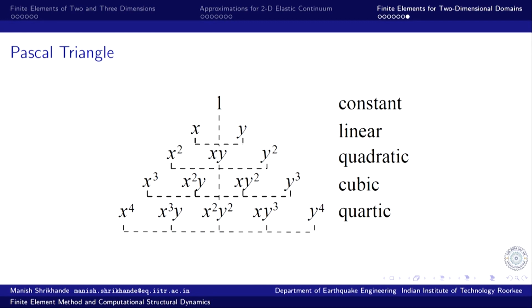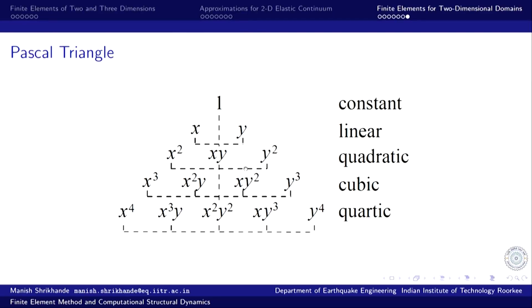So, in the approximation, of course, some of the spurious higher order terms would be there in order to ensure the constraint requirement, but we rarely make use of finite elements which are based on polynomials complete beyond second degree, right. So, when we say it is complete up to second degree, I need to have this constant term, I need to have this linear term, I need to have this linear term, and then I need to have this x square, x y and y square, all 3 quadratic terms.